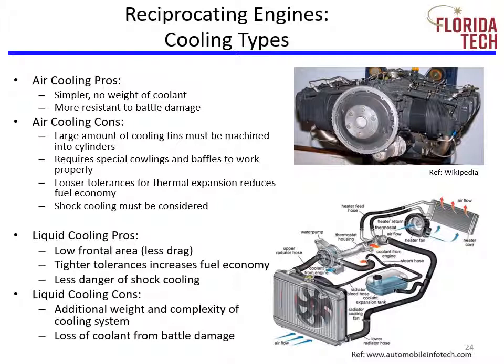Some of the pros and cons of air cooling are shown. Simpler, no weight of the coolant, more resistant to battle damage. But the cons are large amounts of cooling fins must be machined into the cylinders, requires special cowlings and baffles to work properly, looser tolerances for thermal expansion reduces fuel economy, and shock cooling must be considered.